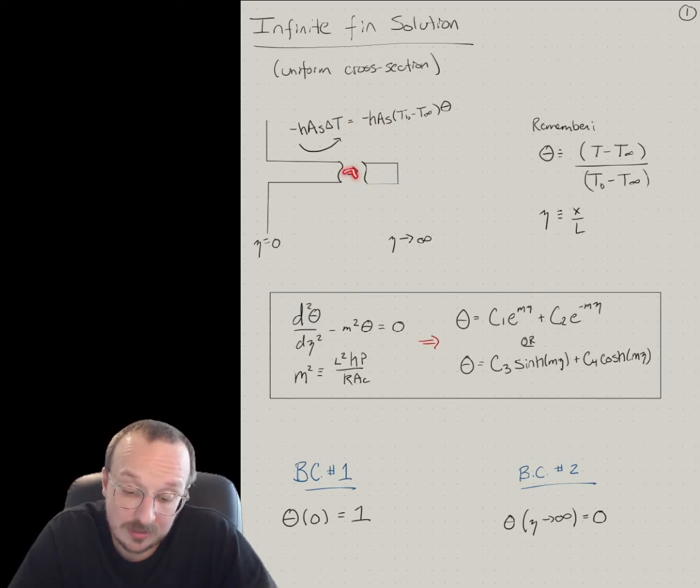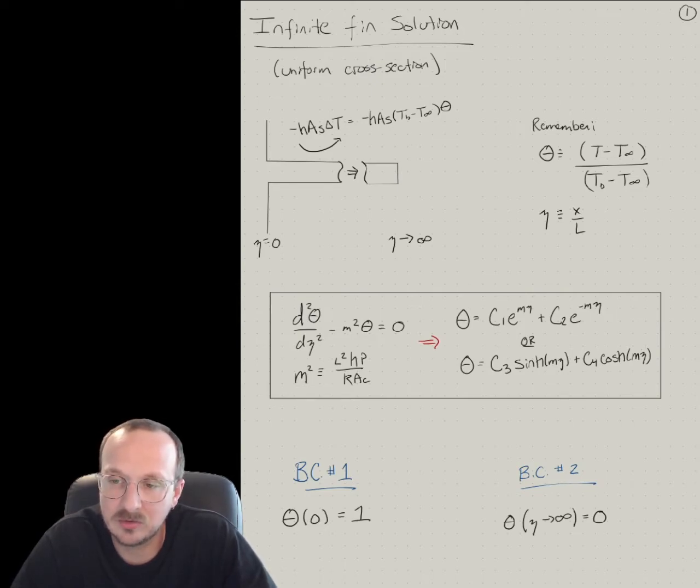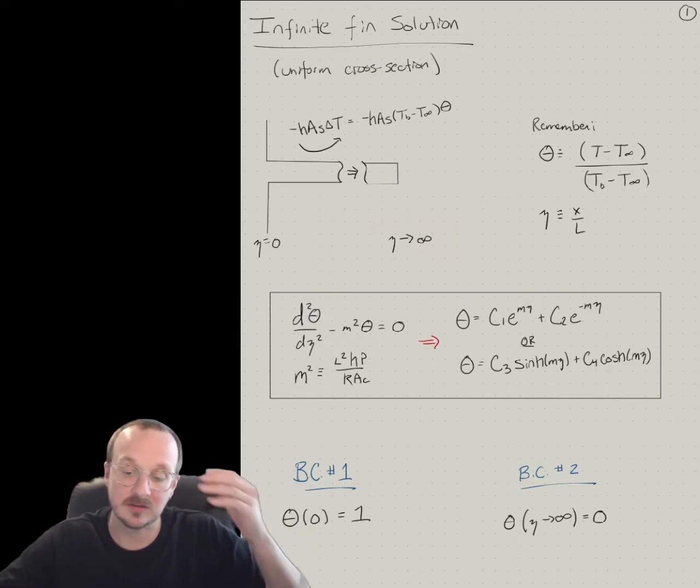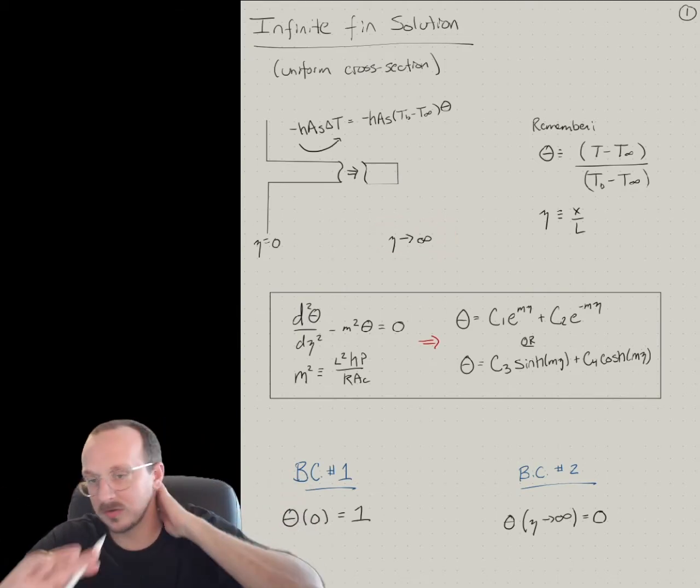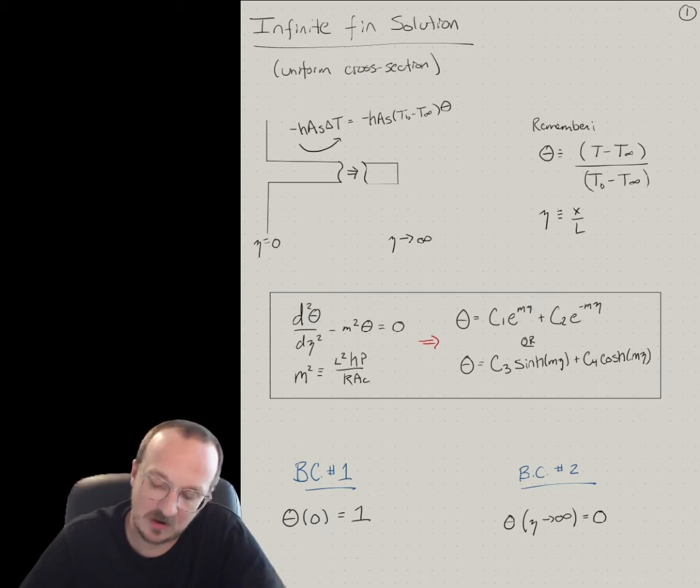We don't know the length. So z goes from 0 to infinity. Kind of interesting because then you're saying L equals infinity. You can ignore that for the infinite fin because you'll see why. Let's just assume that we normalize by an infinite length scale. But no worries. Let's plug it in and see how the math works out.